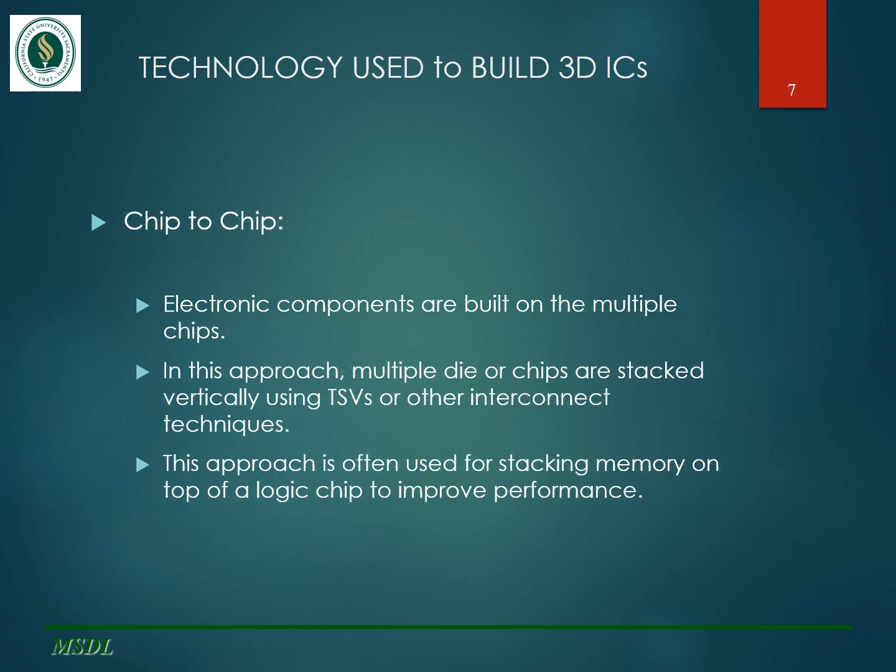Chip to chip. Electronic components for this technique are built on multiple chips. In this approach, multiple dies or chips are stacked vertically using TSVs or other interconnect techniques. This approach is often used for stacking memory on top of a logic chip to improve performance.